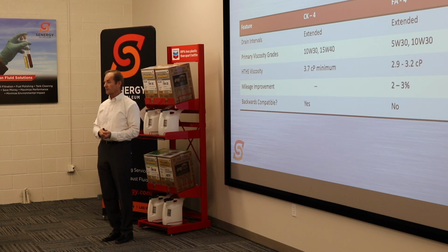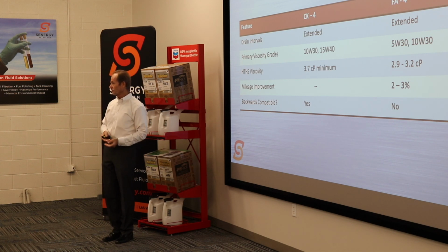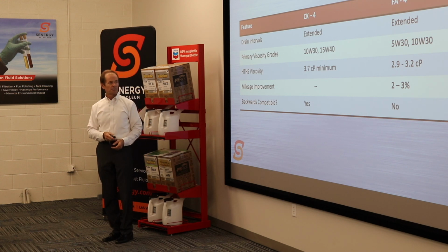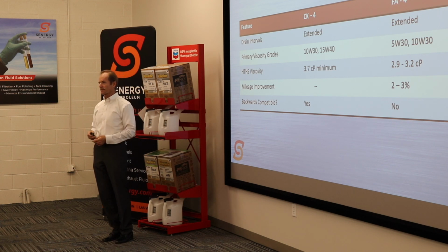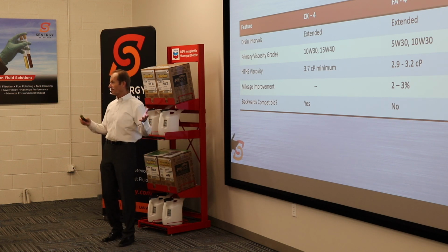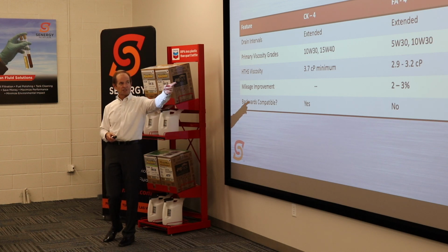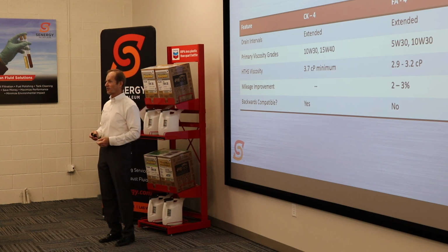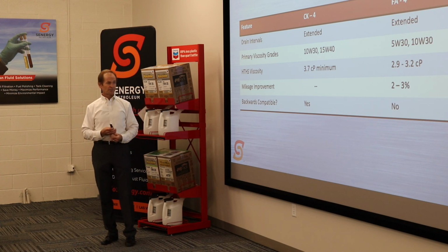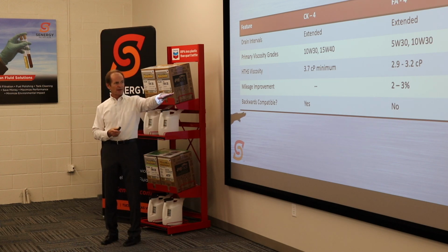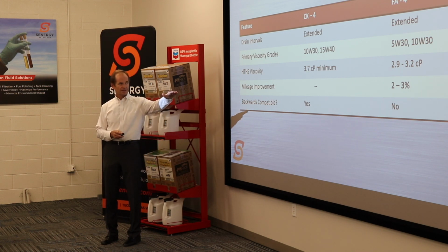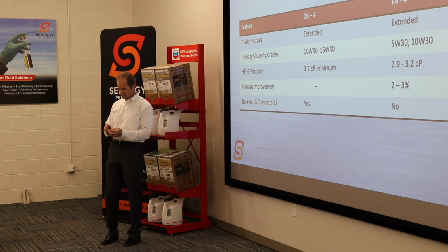Detroit Diesel is a big advocate of these FA4 oils, and they will allow you to go back, I think, about half a dozen years in their engines and use it. And we know of some oil companies and some additive companies have done some fleet testing, even in mixed fleets with equipment going back 10 years old, where they're using an FA4 oil and they didn't have any engine problems. So you'll hear people talk about that, but by and large, it's not inherently backwards compatible.